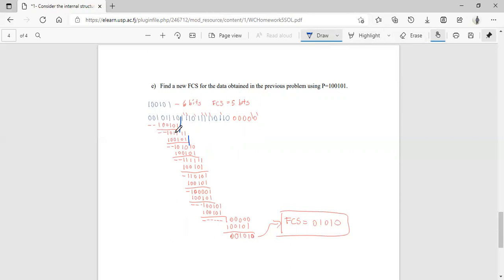After performing the XOR operation, I'll bring the next set of bits down. I'll continue doing it until my last bit, as long as the remainder data set after carrying the value down is not less than my polynomial size. You can see that after each stage, you are getting some values that you bring down. You'll continue doing it until the last bit.